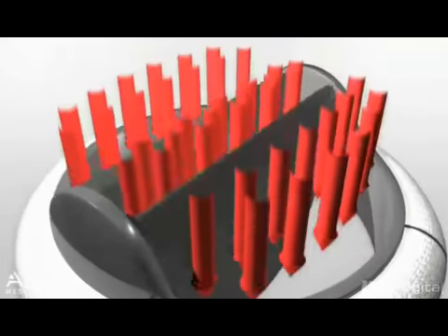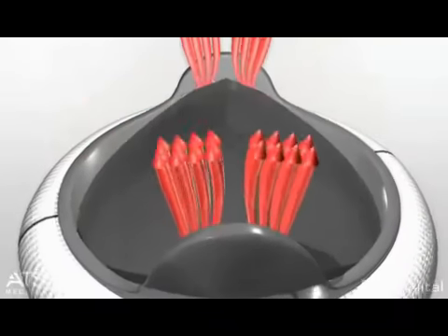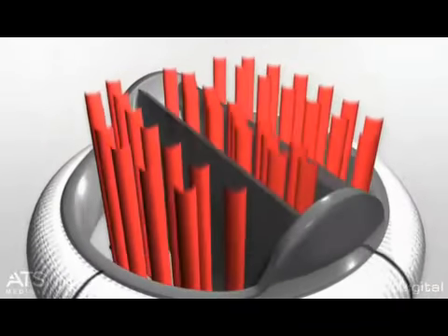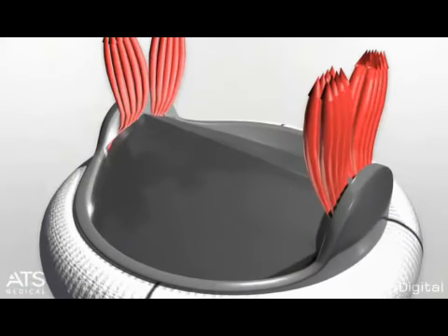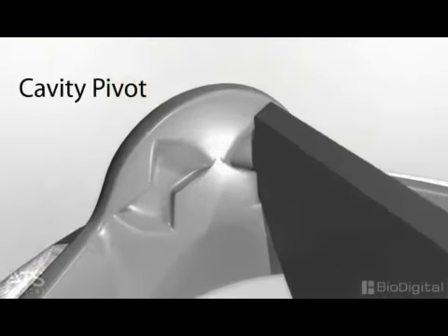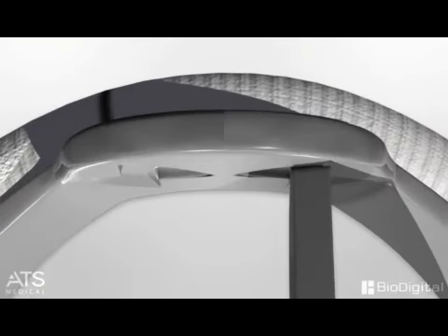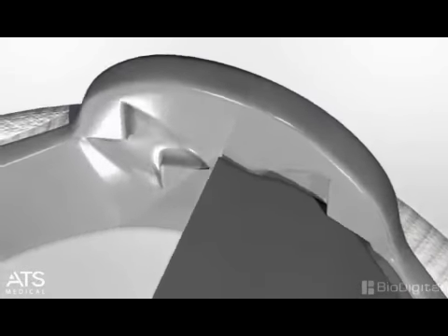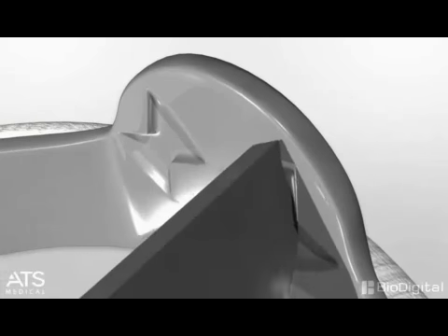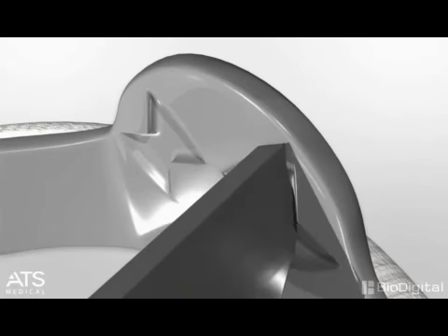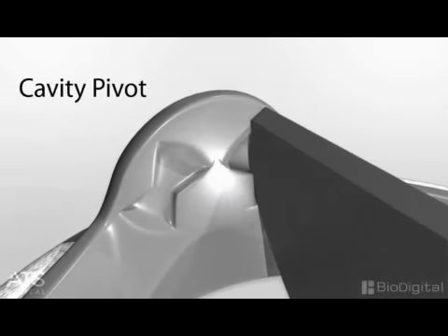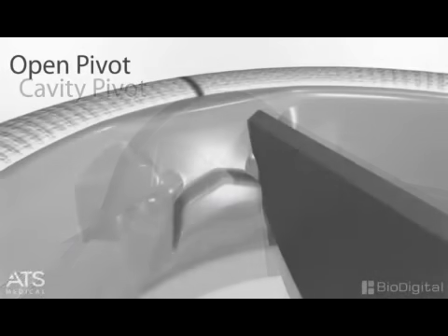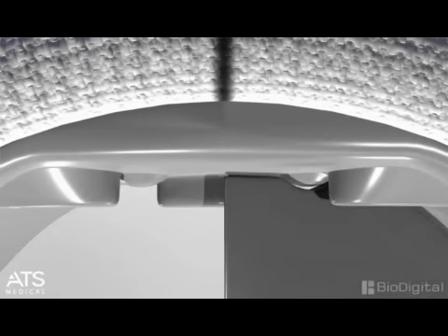The blood interaction with mechanical heart valve pivot design is critical to valve performance. Managing flow quality, especially through the pivot, is the best way to minimize potential clot formation. Bileaflet cavity pivot recesses, used in all but the ATS open pivot mechanical valve, have long been held as a potential source of thromboembolic complications. These cavity recesses require scraping by the pivot ear and flushing by high-velocity leakage jets to avoid the accumulation of thromboembolic components. Improving the design of the valve pivot provides the best opportunity to reduce this inherent weakness.